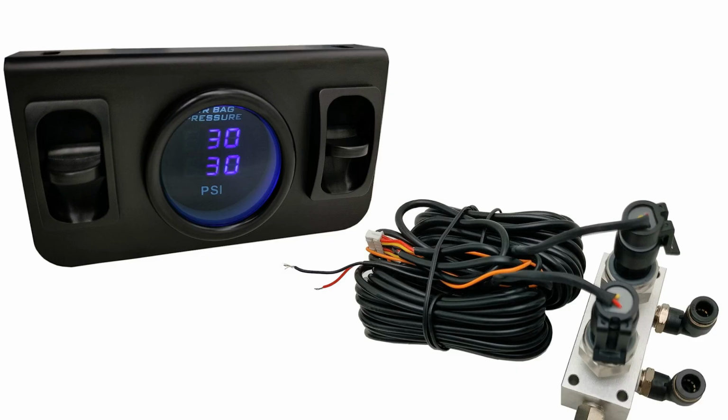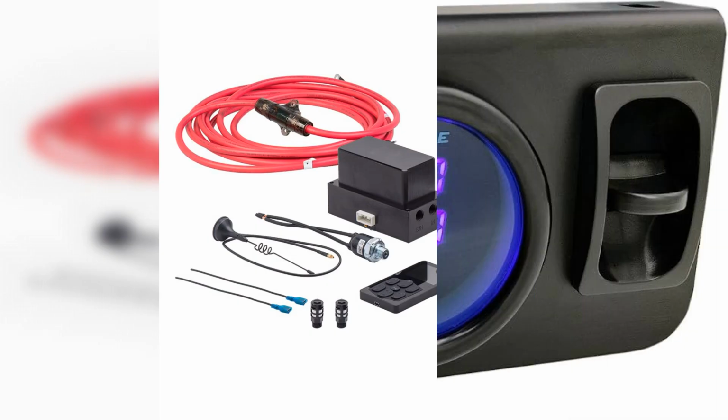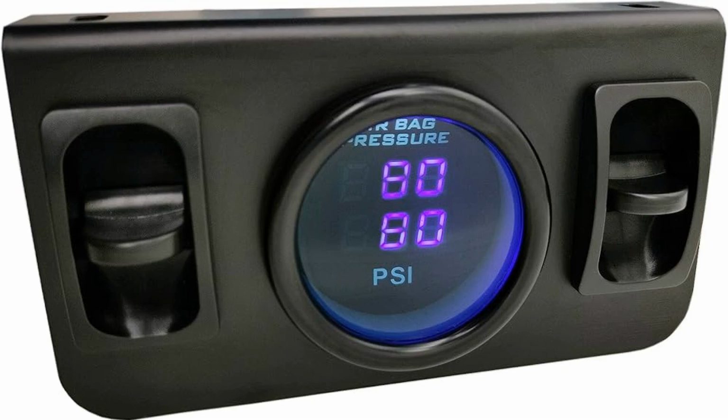Device. The air suspension of a modern car consists of a compressor, used to create air pressure, a receiver, which stores a minimum supply of compressed air, filtration and drying module. To prolong compressor life and to ensure proper operation of all valves and sensors, only purified air is supplied to the system. As the air temperature rises during compression, condensation forms on the walls of the metal receiver. Therefore, the air is dried before it is fed into the system.